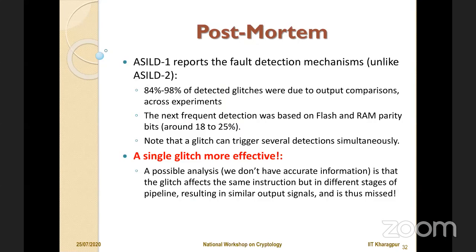Suppose you're doing a fault injection which is affecting a multiplication. You are doing a redundancy check, which means you are doing this computation twice, and since you have got two cores, you are using both the cores for your redundancy check. Now when you introduce the fault, the computation is present in both of these cores, but maybe at different stages of the pipeline.